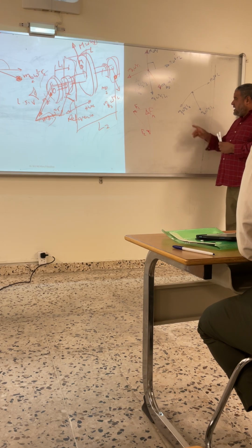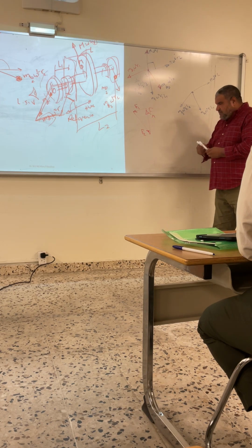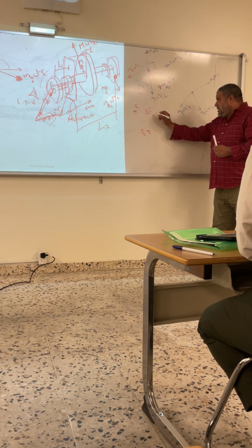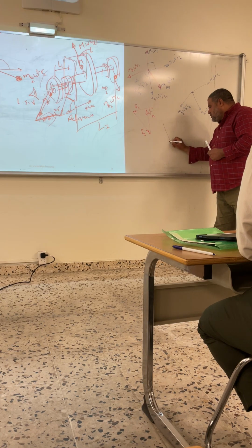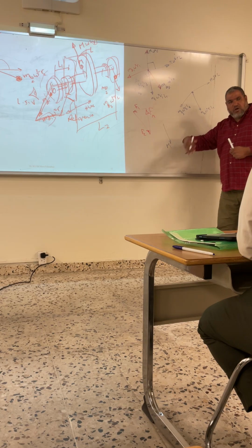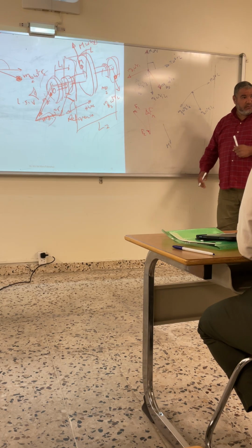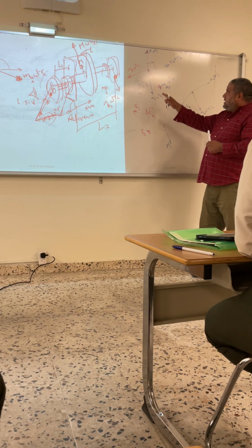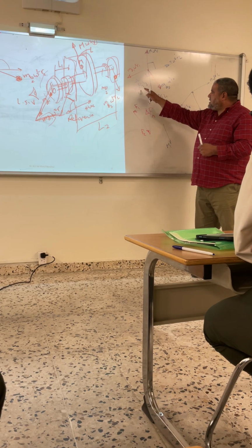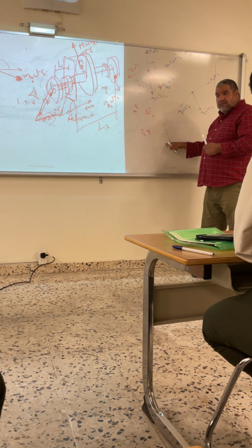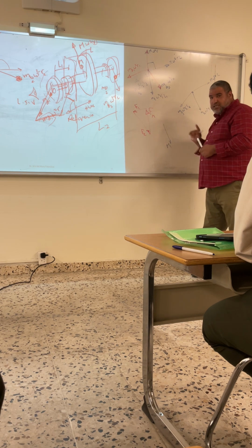Now guys, take F1 and rotate it. I'm going to make it in the blue color to be consistent with what we decided here. That F1 here, I'm going to draw M1 here, which represents MB1 omega square R1 L1. Clear? Now, what did we say? MB1, how was the moment? The moment was leading. This is why I make 90 degrees in that direction.